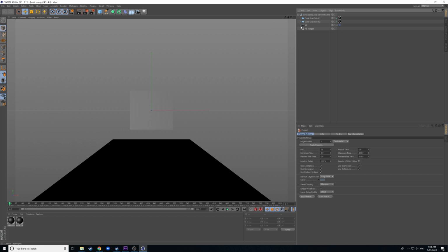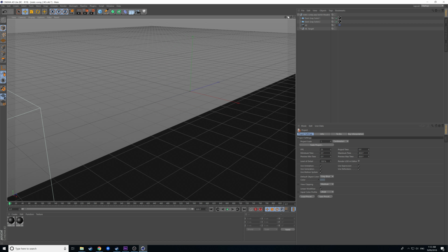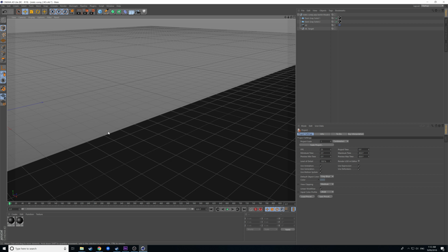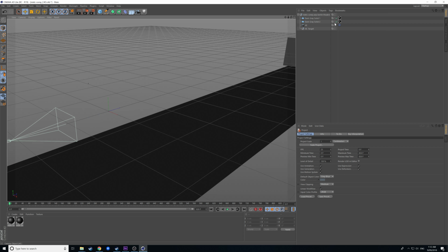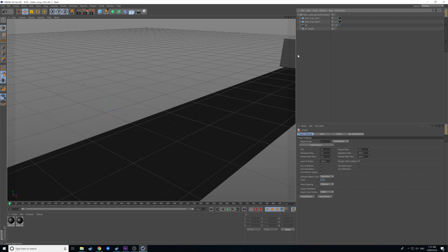And as in the other video, I'm going to turn this tracking to camera off so that we don't accidentally move the position of the camera. This view will get exported to After Effects, and if it's in the wrong place, then the rendering and the composition will be completely wrong. So we want to make sure that we turn that tracking off so that we can jump back to it before we save the file.